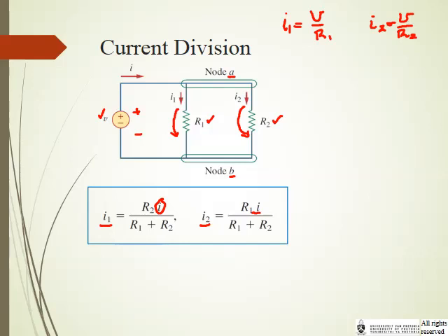Right, but that doesn't give me a relationship of I1 as a function of I. But what is the voltage? We know that voltage equals I times R total. So the current is now the total current, R total, and the supply voltage. Here I is the one we're looking for, and R total we can calculate. What is R total?